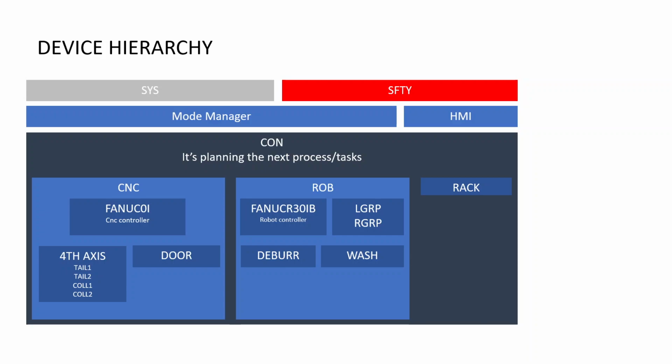If the robot opens its gripper and I can see that the output state is on but I don't see a sensor reflecting that position, I can trigger a warning to the system. And that's useful for diagnostics.